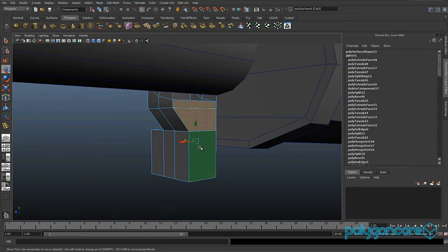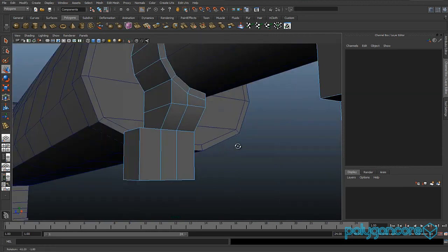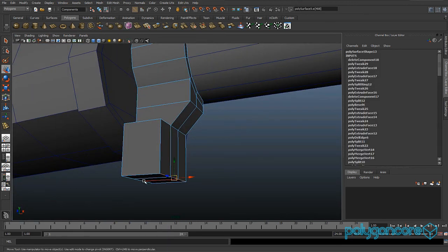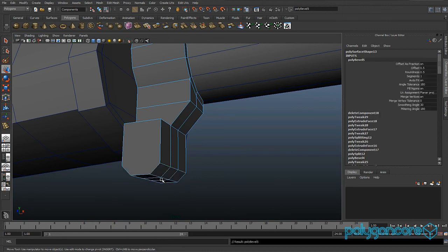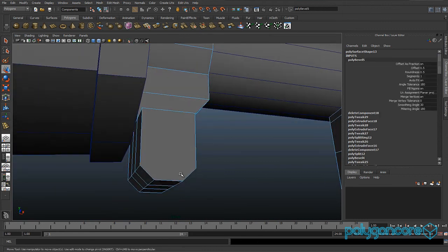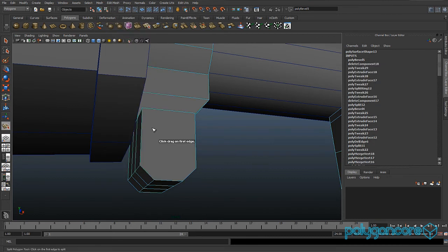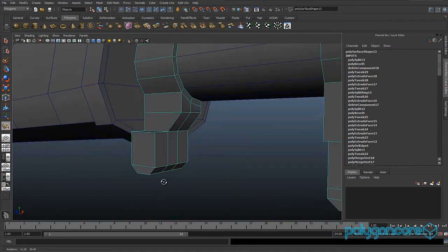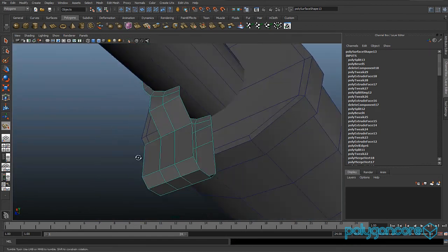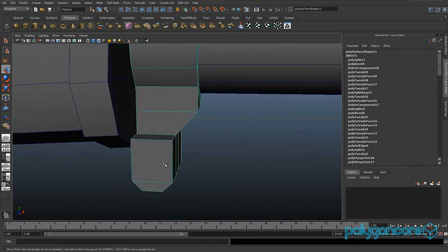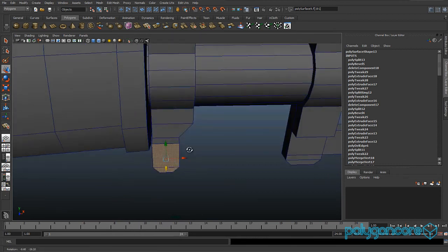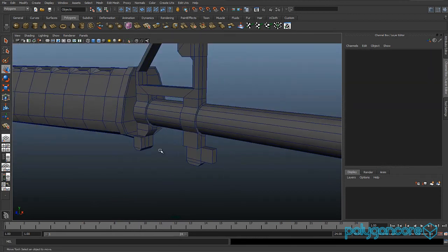Fred fixes it later, so delete these back faces and select these bottom edges here, these ones and the back ones, and you want to bevel, and then you can do a split polygon tool and insert a split from here to here, and then you can select this face here and here and just pull these back, and like I said, just pull them out just a little bit.